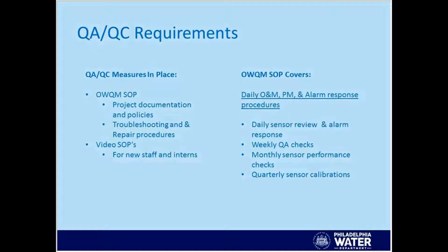The SOP covers the daily O&M, preventive maintenance and alarm response protocols. So the SOP covers the daily sensor review and alarm response. We do a daily review of the network, identify alarms, and everything's prioritized, which alarms get more priority than others.